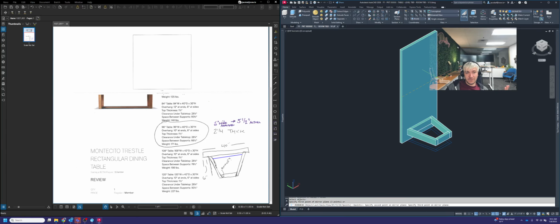The third point has to be on the same plane that you're flipping this across. So imagine you're drawing these yellow dashed lines here. Imagine you're drawing a flat plane in the middle of your table. Just like when you use the slice command or the section view or the section plane command, what you're doing is drawing a fake plane. It's not there, but you're drawing it in and telling AutoCAD this is what I'm using to flip over to the other side.